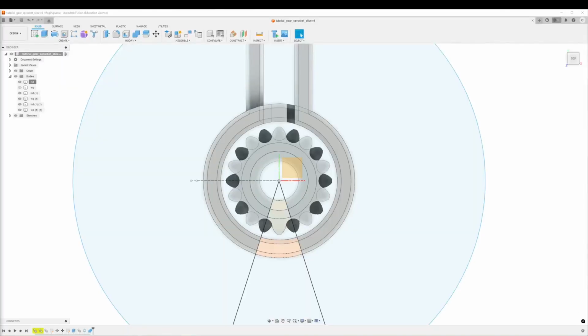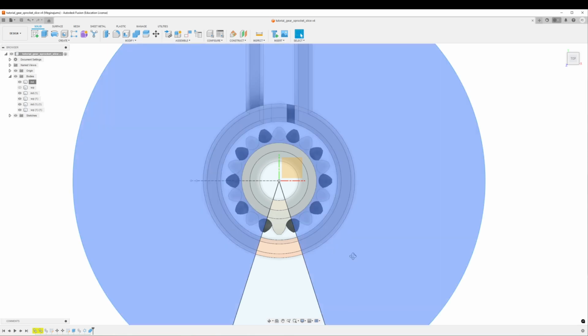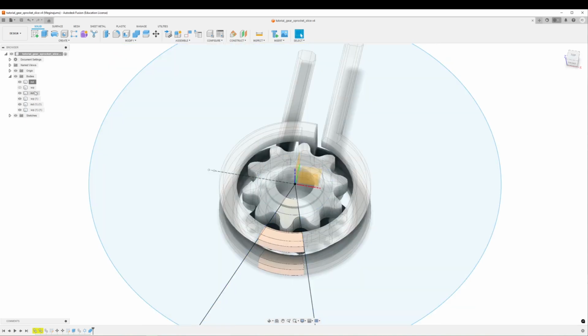Geometry is the beginning and the cornerstone of every simulation, so we need to start by preparing our geometry for the simulation. First, you need to make sure that your CAD files have been created correctly. Make sure that the whole geometry has been cut at the same plane, the black lines you see here. Even small deviations of the geometry from the cut plane can lead to problems during setup or calculation.